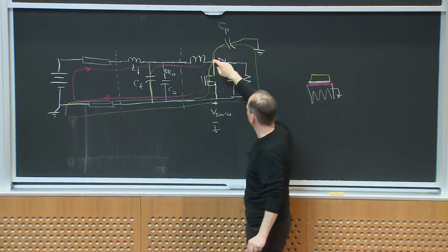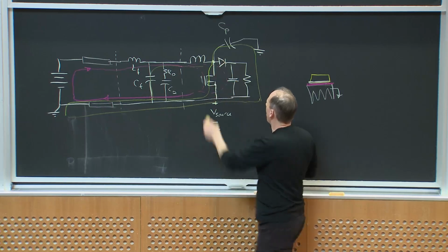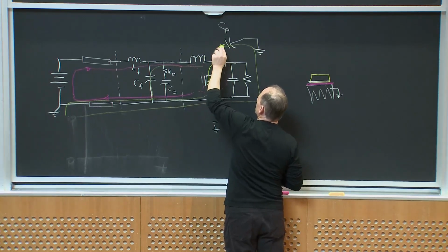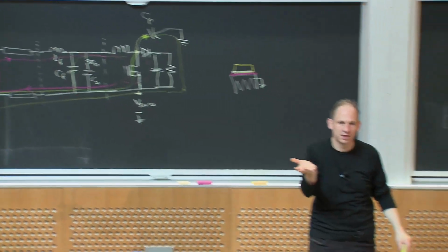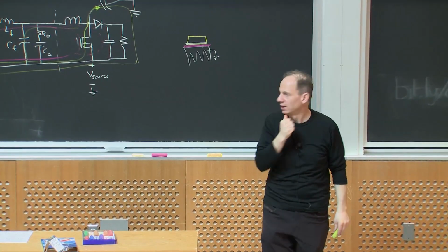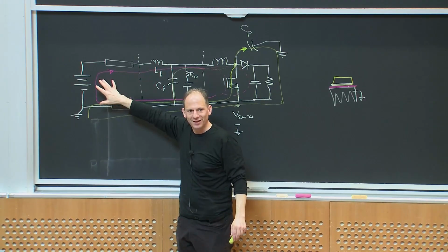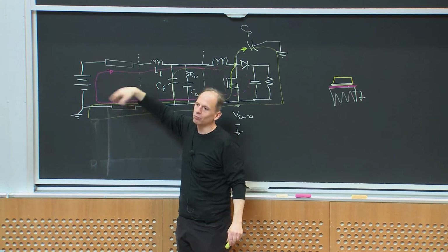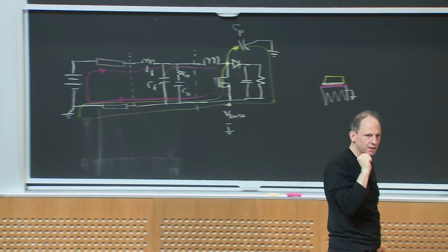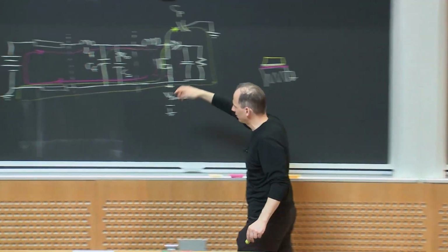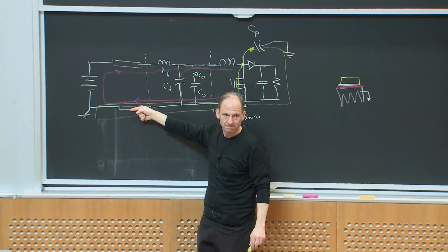To the extent that this node is slapping up and down with respect to something very close to ground, I'm going to get a bunch of current through this parasitic capacitance at high frequency. Not DC current, just AC current. And if this lead is kind of long, that looks just like an antenna. And I'm right next to my radio, so I run into electromagnetic interference that I'm causing, not necessarily through this lead, but current coming through the other power lead.